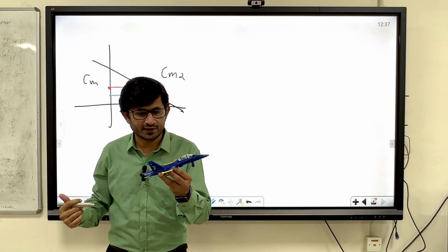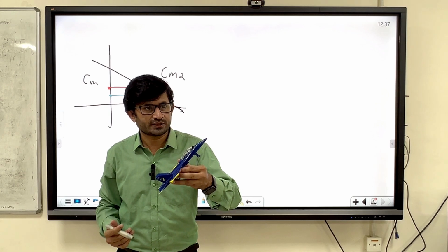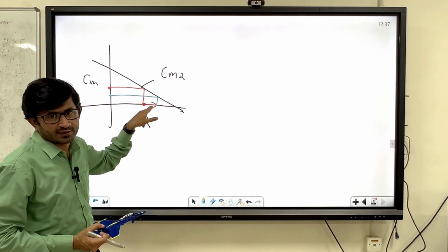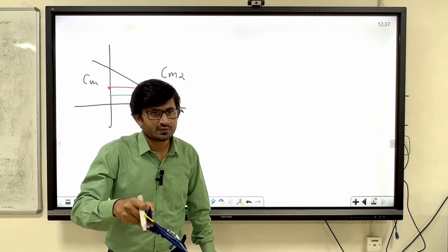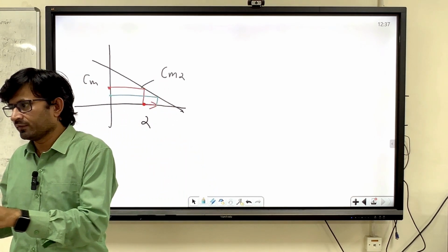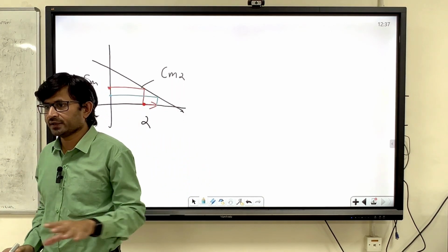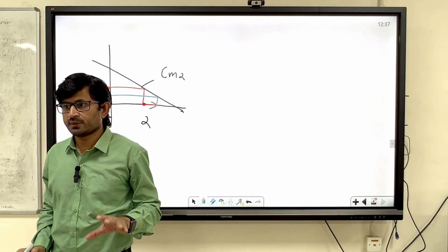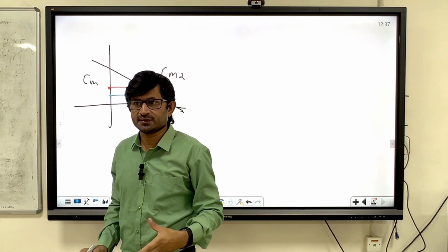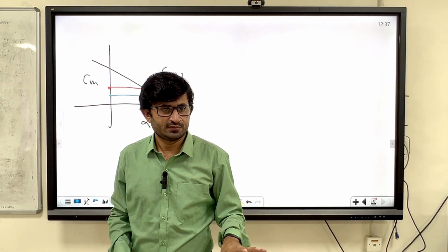At one angle of attack I am flying. When a disturbance comes, the angle of attack increases, and now the aircraft shows the tendency to push the nose down, and Cm is going down. Cm down is what? Negative. So that kind of feel you have. But as of now we are not getting this. Somehow I want this, but in the present case we have done the wing alone only, which is the unstable case.